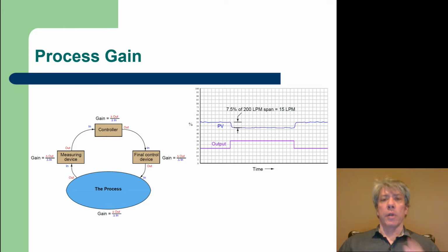Now, in controllers in industry, they don't hardly ever work with the actual variable itself. So it's not like you would get in the speed of the car if you were to put a PID controller in place of you to control the gas pedal. Instead, what you would get is a percentage.